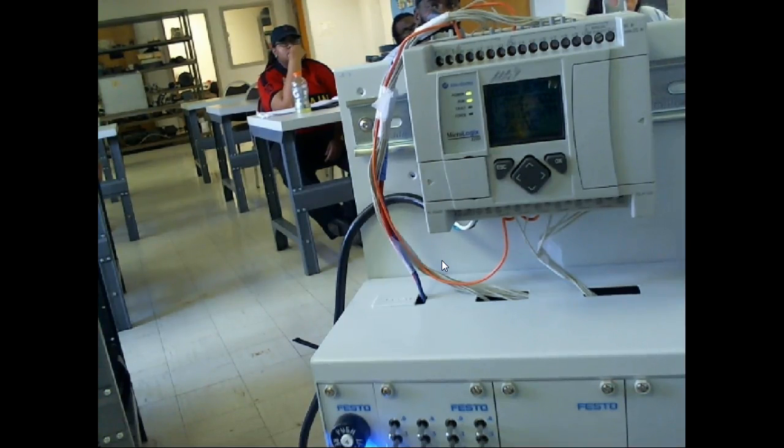And then the outputs, you don't power the outputs off... You never, or try to never, power the outputs off that little internal power supply, right? You understand? No, I'm going to say you can, as long as you don't exceed the ratings of the internal power supply. But they recommend that you don't run the outputs off the internal power supply, that you actually have an external power supply for that. That makes sense? Everybody okay?